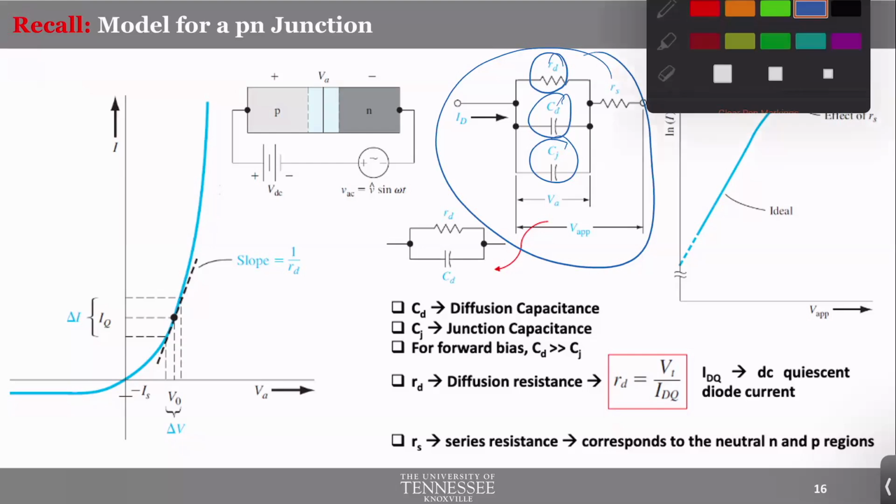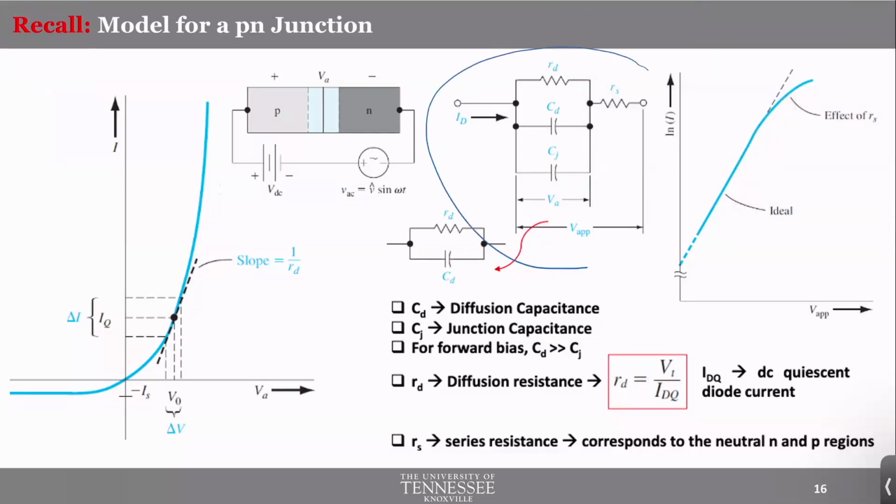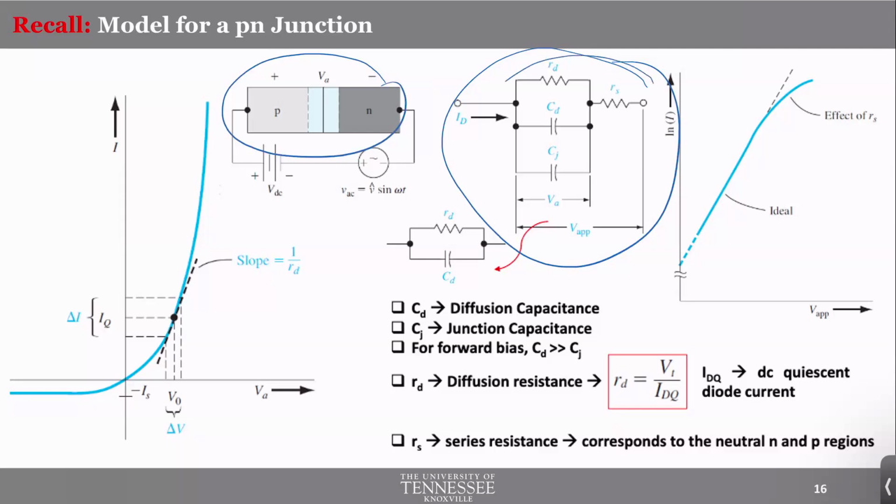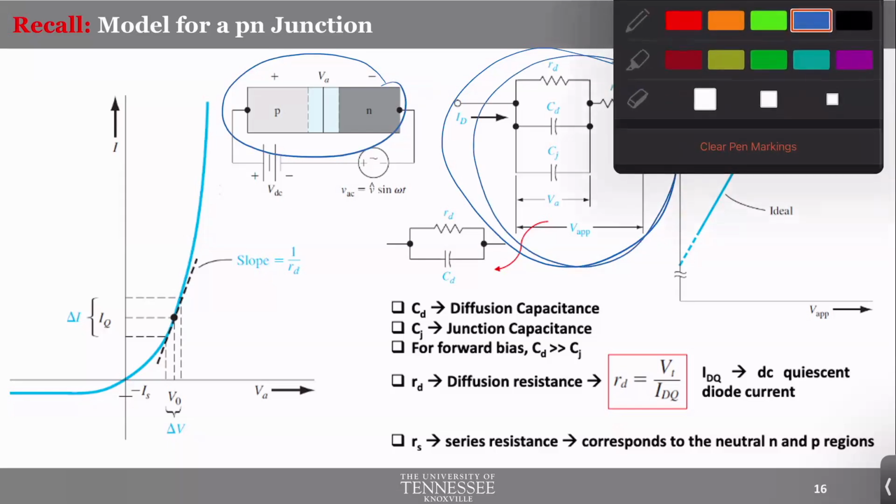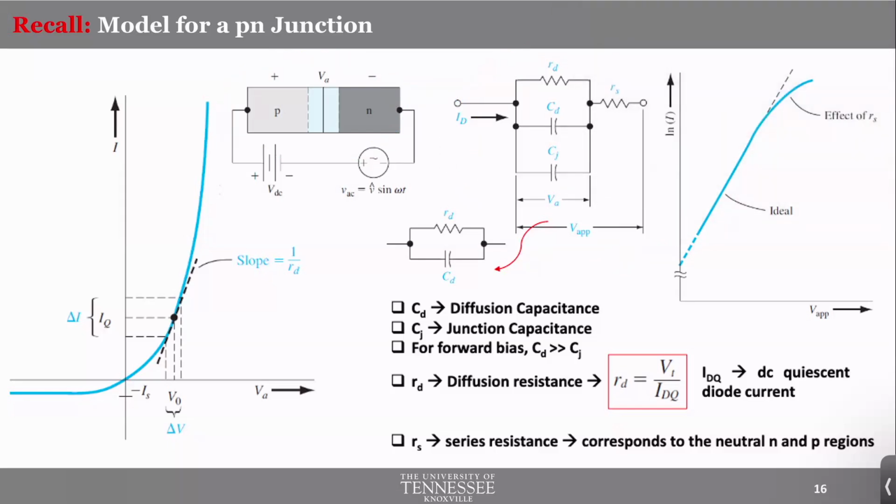So the concept of using an equivalent circuit is to represent different physical phenomena that occur within a device with electrical analogs, meaning resistors, capacitors, inductors, voltage sources or current sources, whatever works. This used to be a way to solve mathematical problems or circuit problems. So you needed to represent this diode in this form using basic circuit entities so that you could do KCL, KVL, or other circuit theory based approaches.